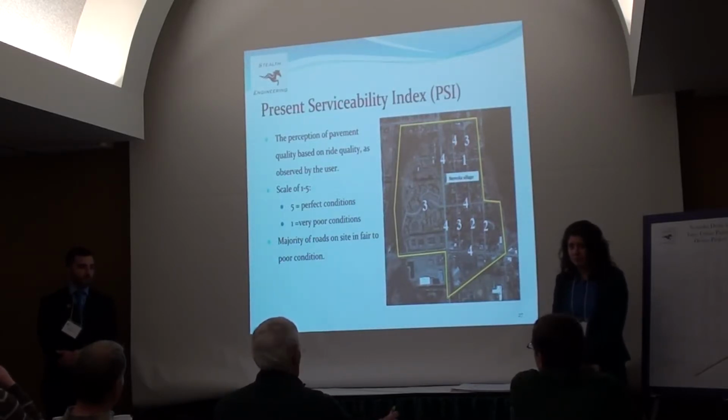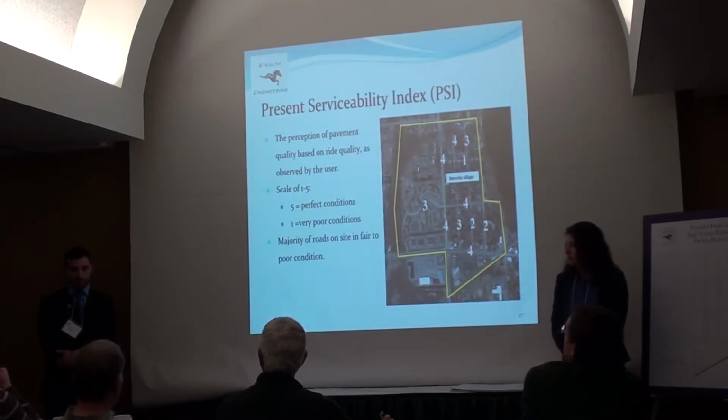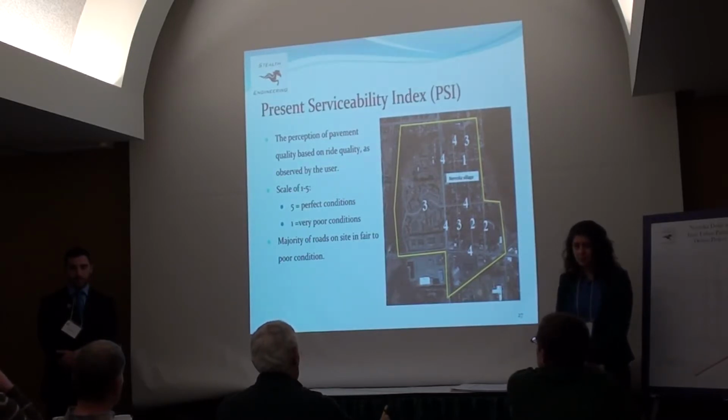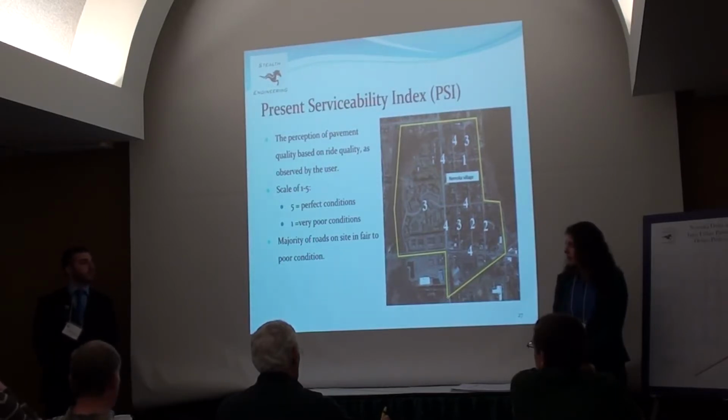You think that the overlay is going to last for 20 years? I think it will if the road is treated before the overlay is placed down. I've designed it and I've also checked it in the program MEPDG to ensure that the overlay will last with the current pavement conditions. So you're going to do some pre-treatment to the existing pavement? Correct. Any patching and any areas of severe distress, we would encourage a localized mill and fill.